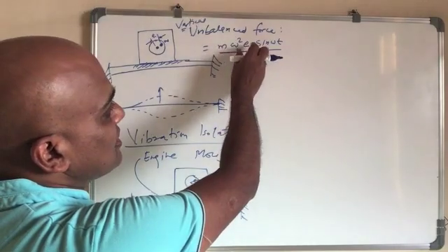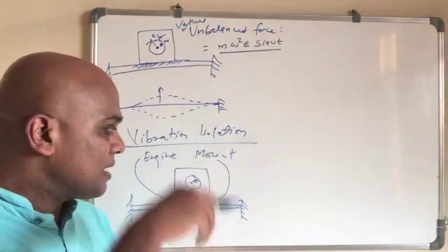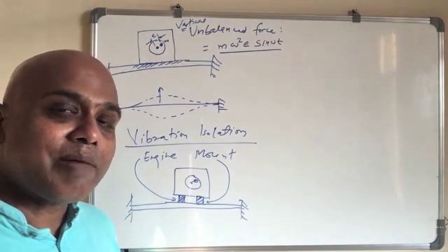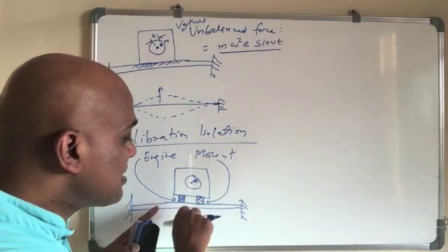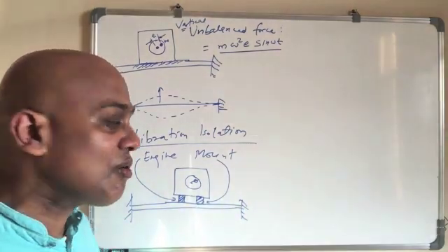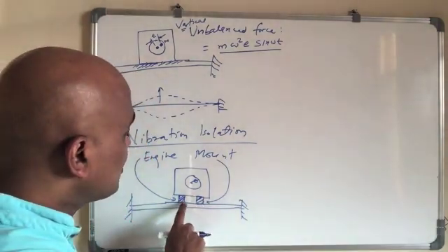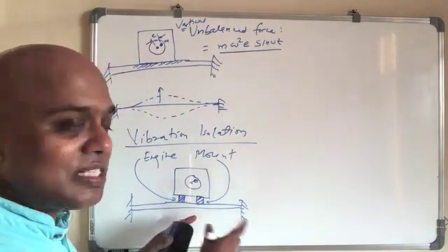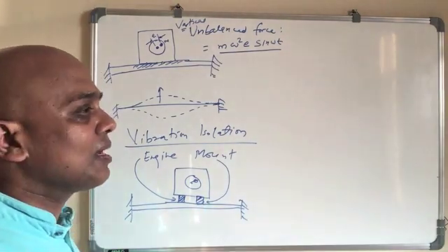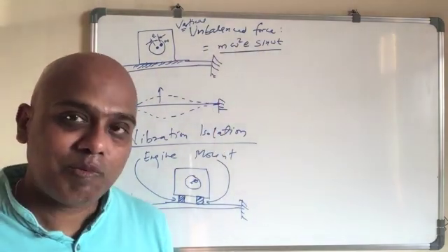So whatever the force you get here, the amplitude here is m omega square E. If the same force is going to go there on this one, because of the dynamic load, there may be fatigue, for example, in the structure, it may fail. So we want to reduce the amplitude of the dynamic force. And for that, we want to use a spring damper here, in such a way that the force transmitted to this structure or to the ground is less than what the force is. So that's what we want to do.